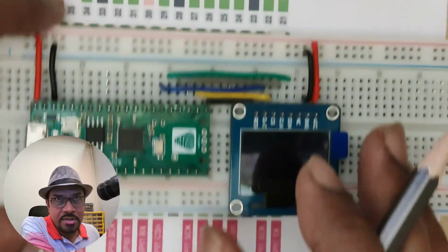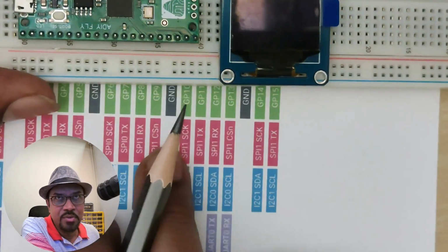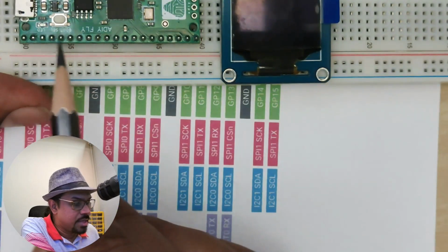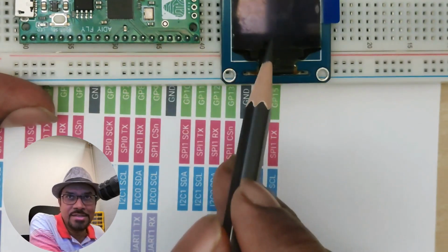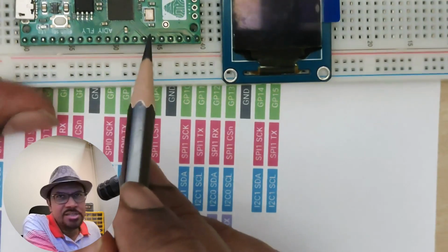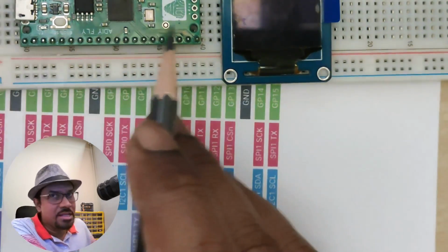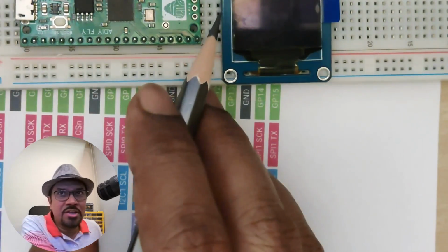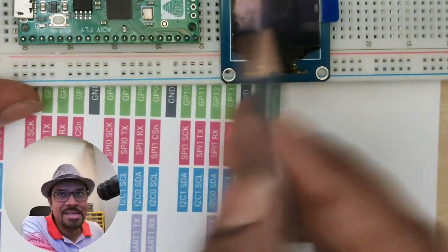You can see that your Raspberry Pi Pico has the same SPI connectors below. That means you can also use the connections below here. Make sure you have the CS connecting to CS, TX connected to DIN, and the RES can be any GPIO pin, and even the DC can be any GPIO pin. Just make a note of that GPIO pin that you're connecting to. And what else? The CLK to SCK, right? You need to connect to that. So that's what the configuration is.